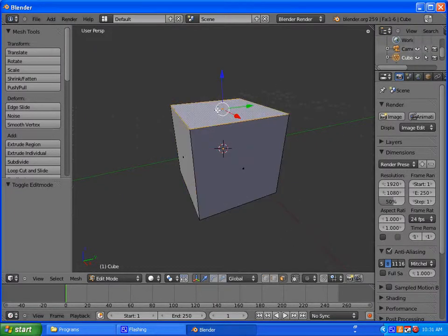You can right click. Down here are basically the select modes. So you have a vertex select mode. Vertexes are the little points. You have an edge select, and you select it by right clicking. And to select more than one, you would hold Shift. Go ahead and just practice as I do it. And then this right here is your face select mode.